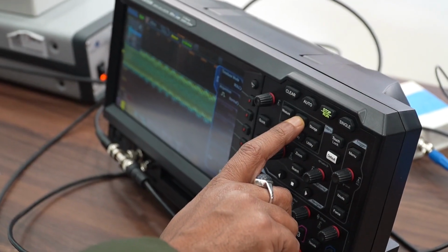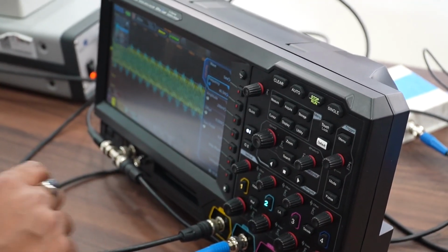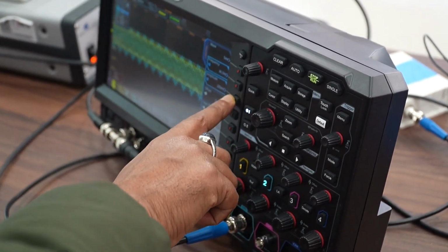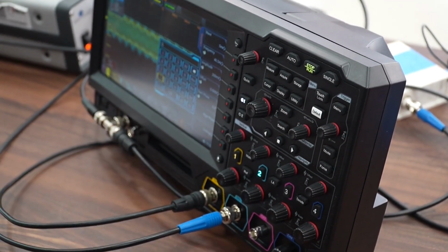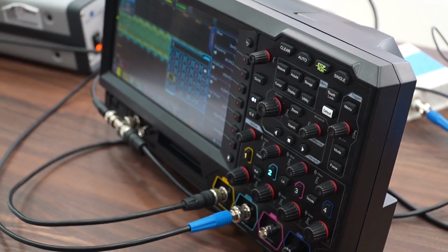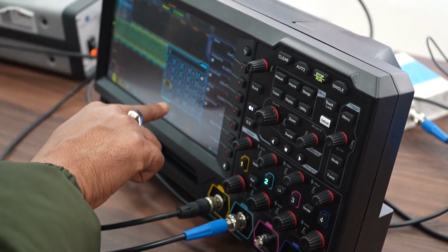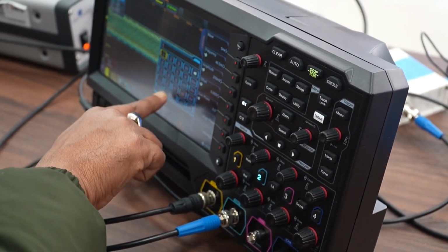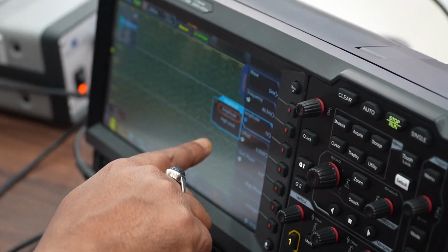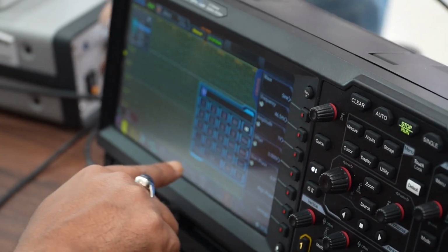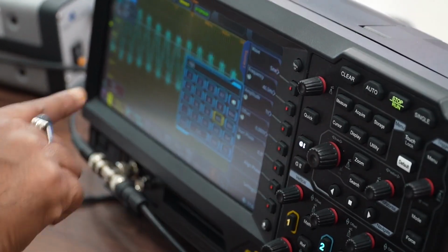How's it going? Have you been able to find the second eigenmode? Not yet. Okay. So where did you go? Where did you arrive? Around 53. No, then you're well above the second eigenmode. So I suggest to look at 44.5 to 47 somewhere. Because the experiment's slightly different. The beams are a little bit bent, for example, and that will change the mode. So it's not exactly identical.